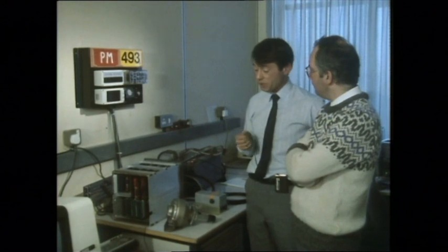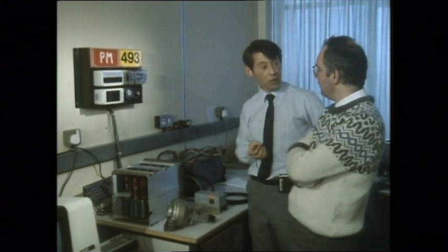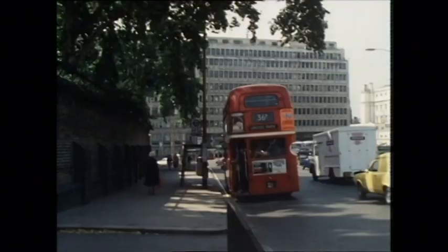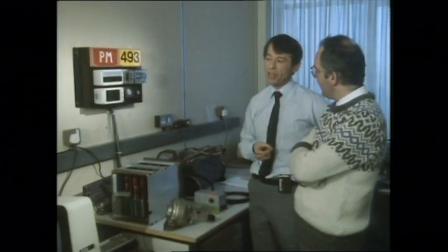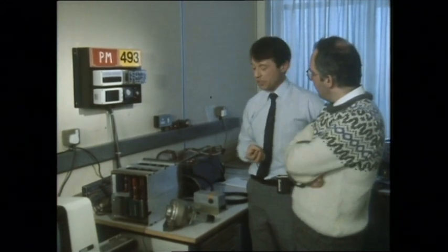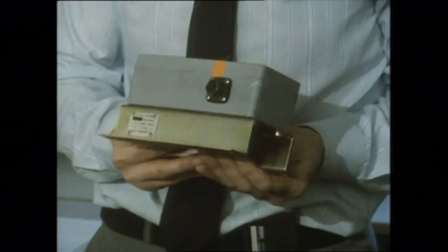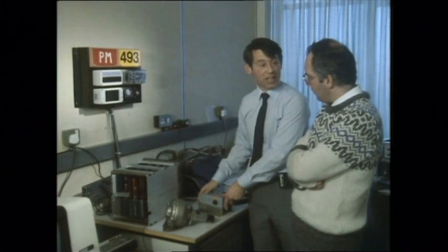But to know where it is, we use basically 2 systems. One is an electronic signpost, which is basically an aerial that's embedded in the road, rather like the sort that are used for traffic light priority type of systems, and entering into car parks. And the aerial transmits an electronic signal to the bus, which is detected by means of an aerial, which is mounted underneath the vehicle. The information comes back to the computer, and so every now and then it gets an indication of exactly where it is.